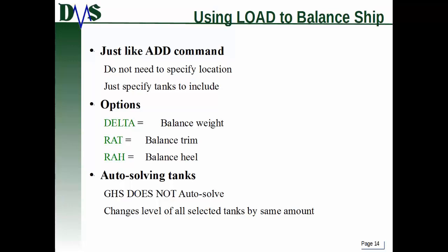Now here's a little bit of a footnote about using these commands to auto-solve for tank fill levels in GHS. GHS does not auto-solve tank levels. It's not smart enough to know the correct way. And what I mean by that is, if you've got a tank on starboard that's too full and a tank on port that's too light, then you might naturally think, oh, okay, we'll take a little bit of load out of the starboard tank and add it into the port tank. GHS is not smart enough to do that.